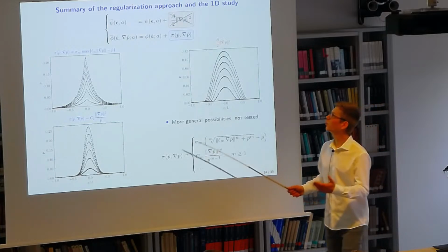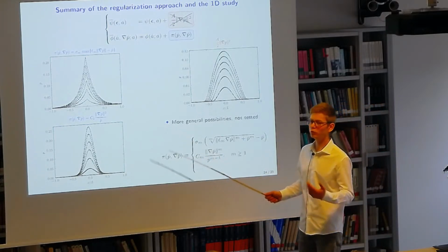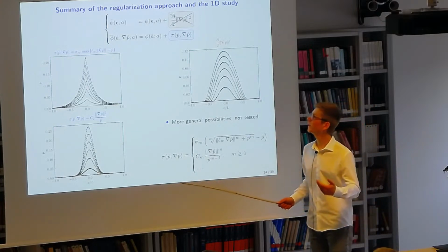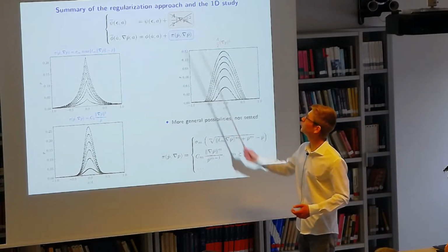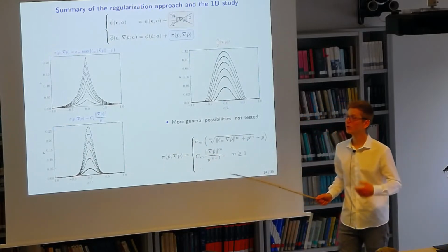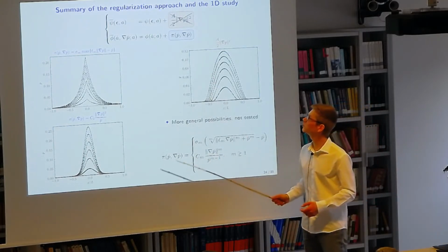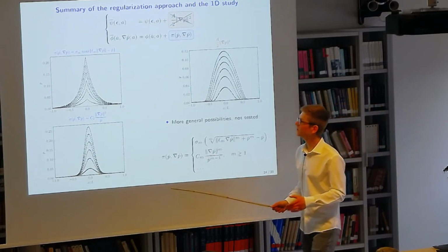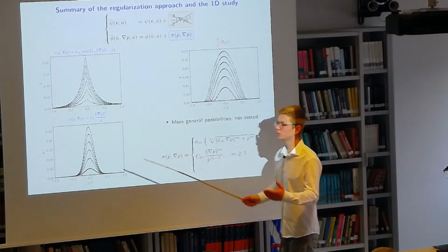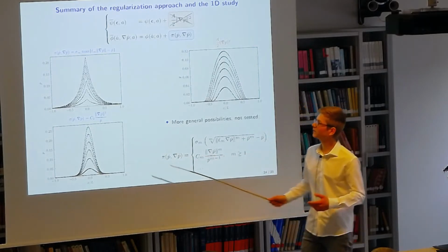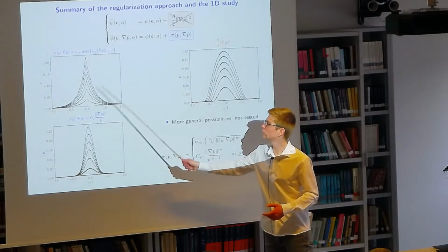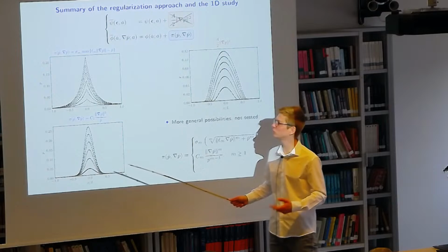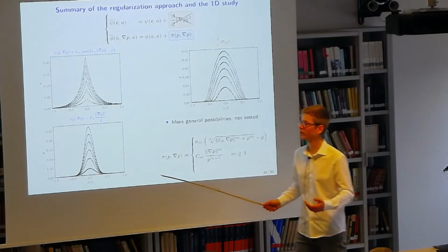In brief, our approach has thus been to involve a cumulative plastic strain, a positive increasing quantity with no finite maximal value, not in the free energy, usually by a quadratic term, but in general in the dissipation potential by this function pi, of homogeneity 1. The previous analytical solution showed us an exponential profile, which means that this plastic band is going to keep its shape at each time step, and so this is an evolution which is stationary.